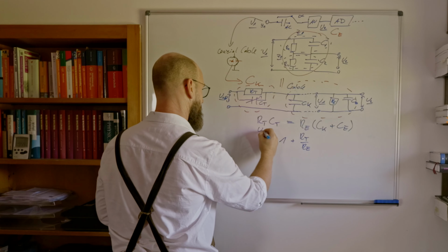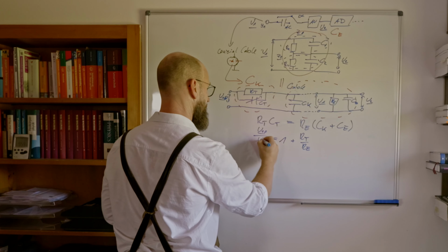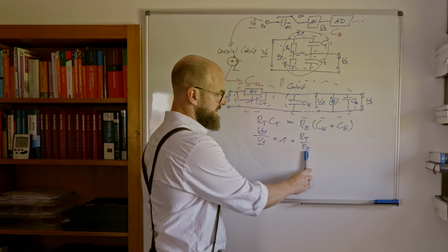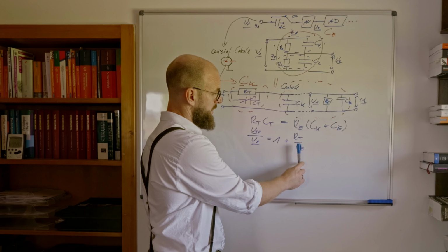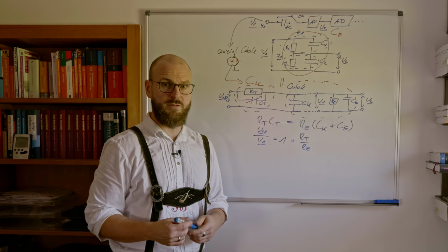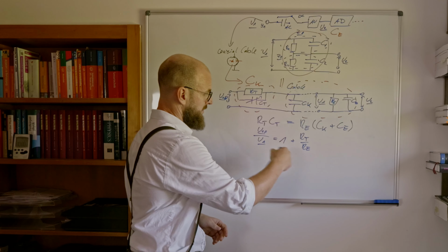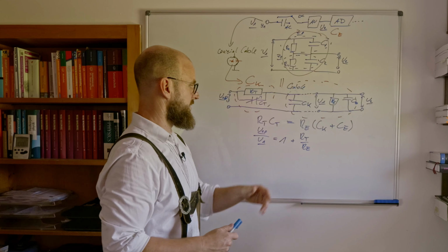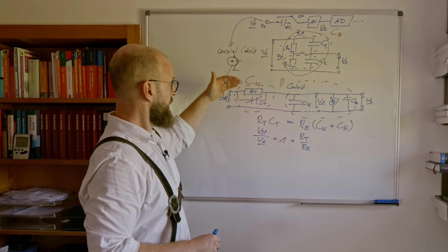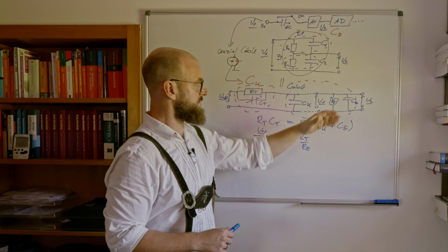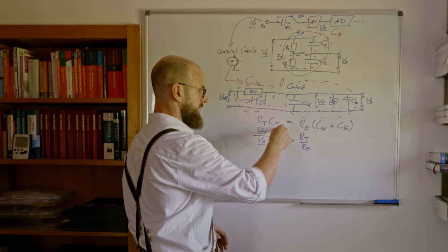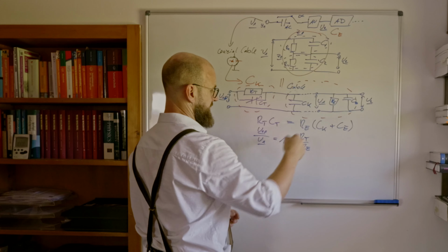There is some ratio of our incoming voltage at the probe to our incoming voltage at the oscilloscope, which you can adapt using the input resistance of your oscilloscope and the input resistance of your probe. So choosing the probe resistance will give you some ratio over here. Often that's a ratio like 10:1 to get down the voltage for the oscilloscope. Having done so, the next step is to adjust CT so that this equation gets fulfilled.